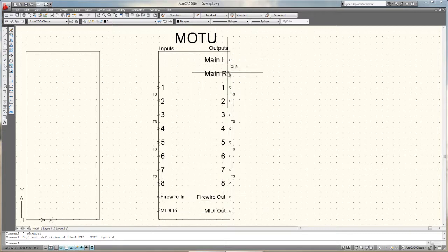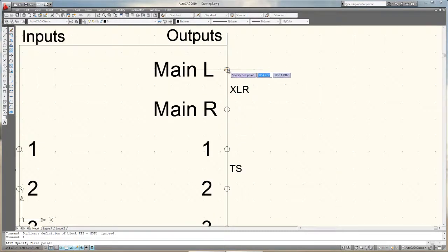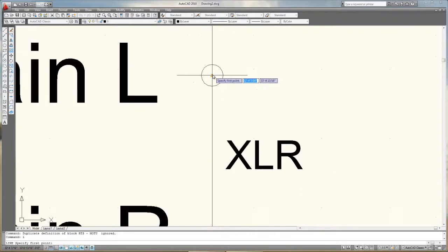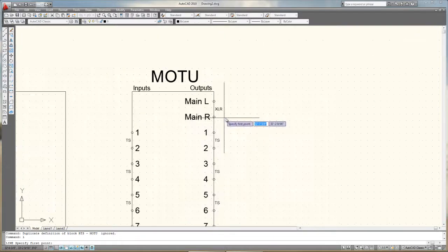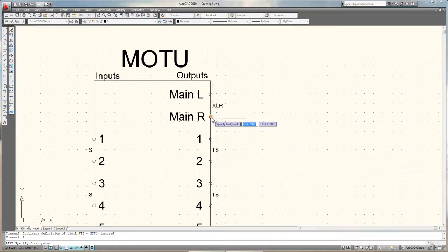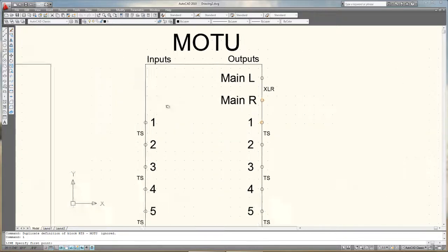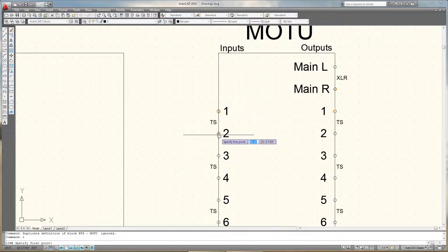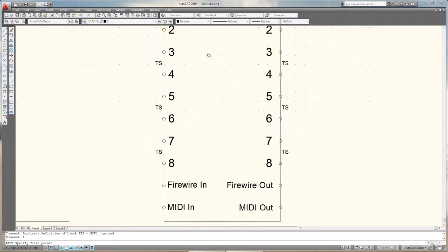And the reason why we have these little circles here is that with circles you can find a center point on them. So it's very easy to get a nice clean spot, and even if you're out further, you can still get right in the center of it. I find it easier than with a square, where you'd have to put an X in the middle to get the center point. So I recommend circles for this, and they're offset by 6 inches each, so that it's uniform.